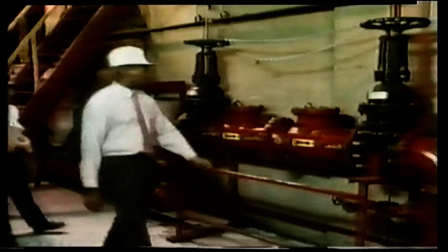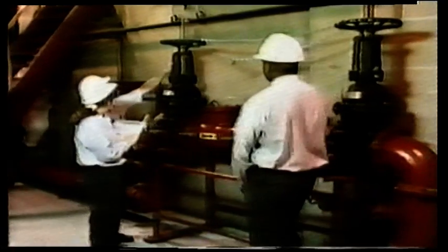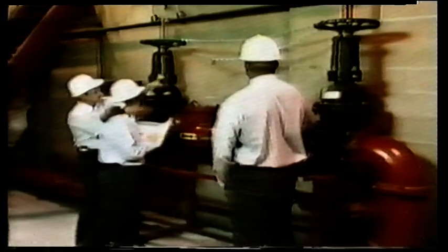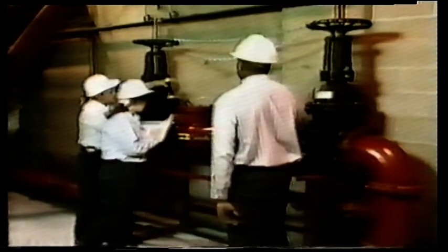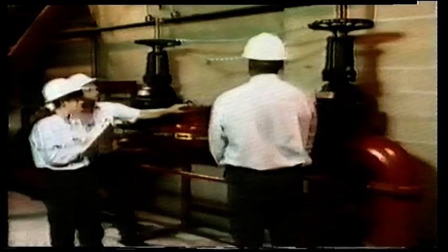These connections to the downstream side of the alarm check are used by the fire department to augment the standard fire protection system with either potable or non-potable water. Because of the presence of Siamese connections and the possibility of contamination by black or stagnant water, the double check valve assembly, seen here, provides the hospital with the protection desired by the water utility. In surveying other facilities, beware of possible chemical additives or antifreeze in the fire protection system, which may necessitate the installation of a reduced pressure principle backflow prevention assembly as the appropriate assembly for a high degree of hazard.